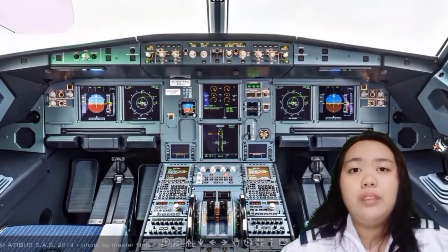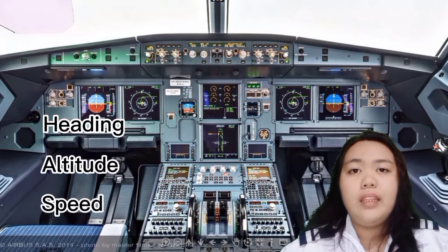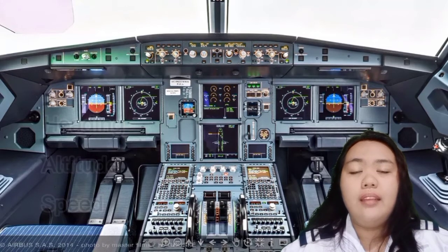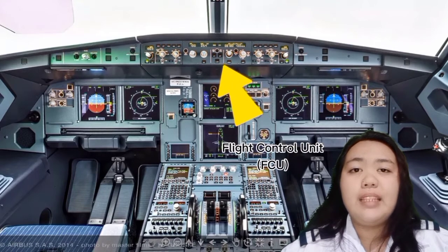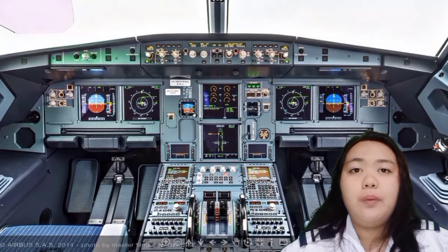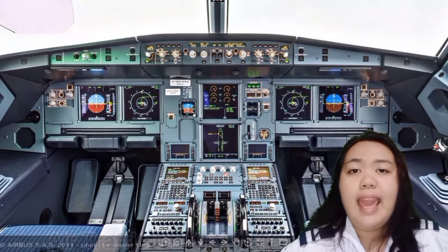In the manual mode, the pilot needs to continuously provide inputs such as the heading, the altitude, and the speed at which the aircraft needs to fly. These inputs are programmed through the FCU or the Flight Control Unit, which will in turn be sent to the autopilot and autothrust computers, which will control the aircraft accordingly. These changes in inputs are mainly instructions from the ATC during flight and for short term only.